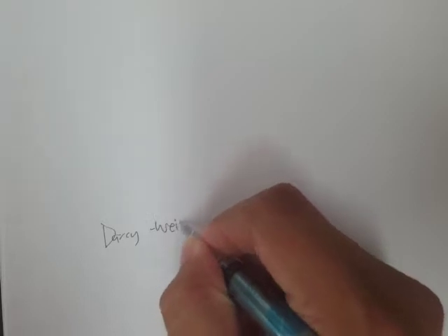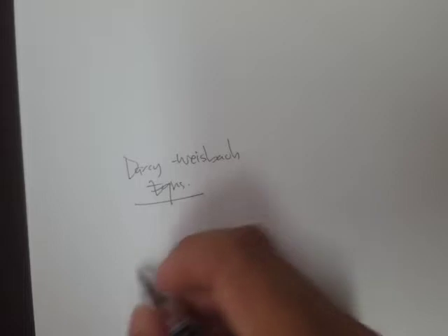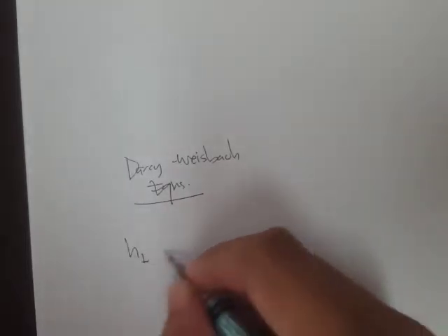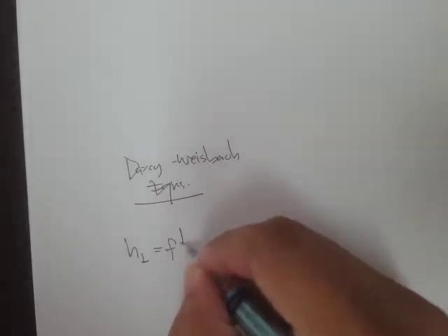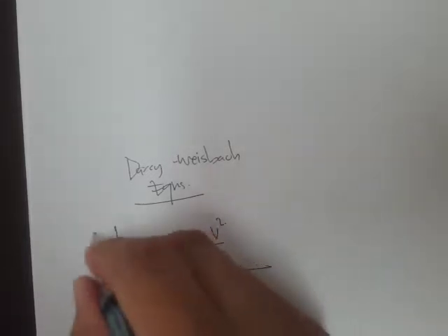All right, now we'll continue our discussion on pipe flow problems. Earlier we have discussed the Darcy-Weisbach equation, and it's given in the form, or mathematically expressed as, HL or HF, depending upon the reference text, f L over D times V squared all over 2g.